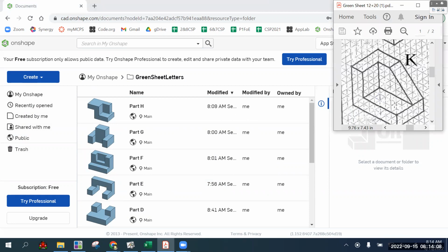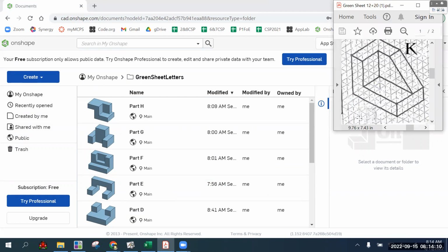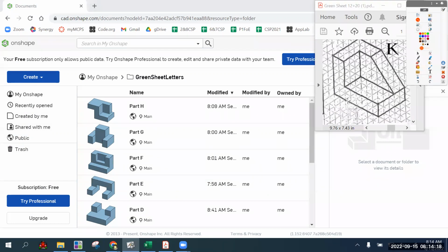And we'll do the same method that we've done for most of them, the subtractive method, I guess, where we're starting with a chunk that is the maximum dimension in all three dimensions. And once we have that block, we're going to cut away what we don't want, which will be this sort of cube area here. And once we have that gone, we can then cut away this slope face right here in another step.